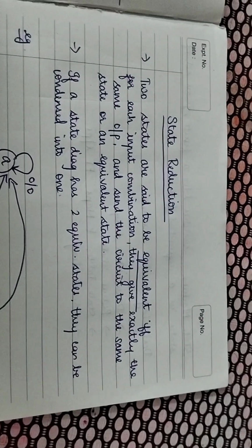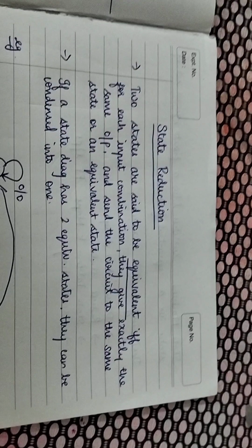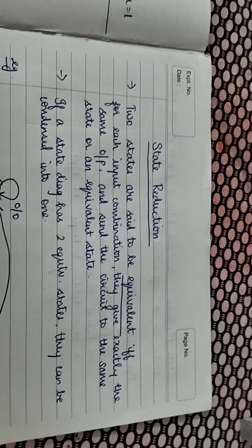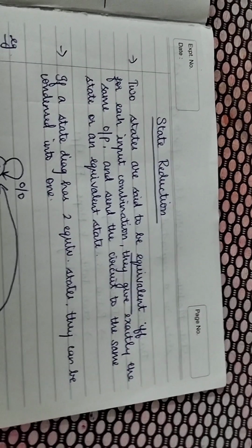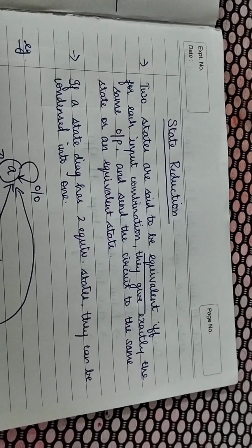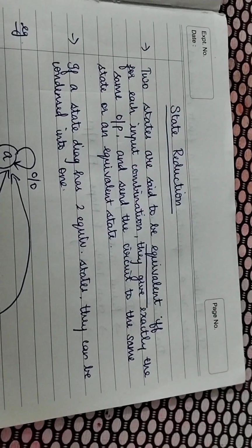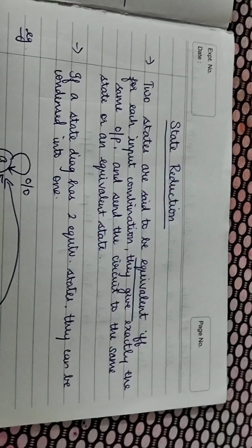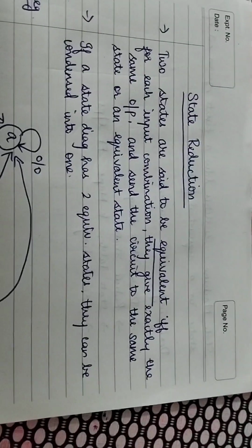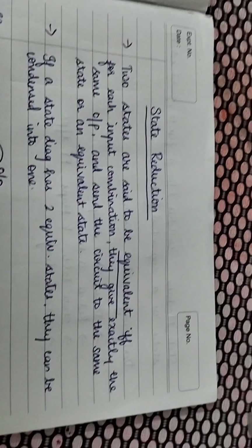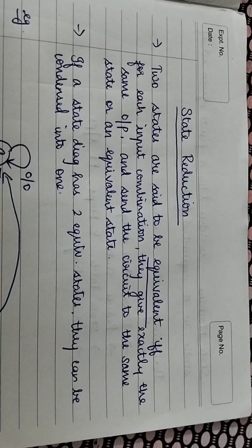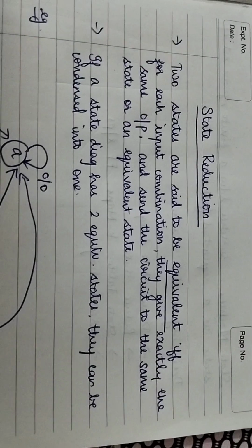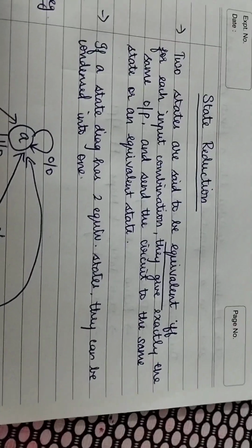But there are state machines where the states are given in terms of A, B, C, D and so on. They are not specific numbers. And you have conditions like if it is currently at A and I give you an input 0, it goes to B. If I give you an input 1, it goes to C and so on. Those are a variant of state machines which we will be looking at. Because the states there are defined in terms of A, B, C, D, it is possible that there are 2 states which lead to the same output under every combination.